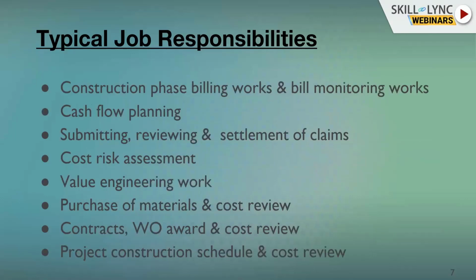Now in the construction phase, the engineer has to do the billing works and bill monitoring works. The contractors will submit the construction RA bills, as we call them, and then the engineer will certify them and the bill monitoring will be done. Then cash flow planning has to be done. Each individual project will go through many months, so in each month, how much cash flow and how much funds are required, that planning has to be done so that the finance department can arrange the funds effectively.